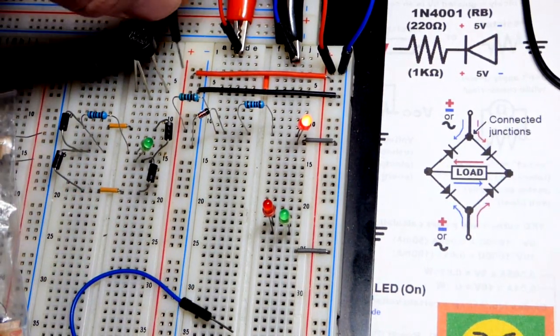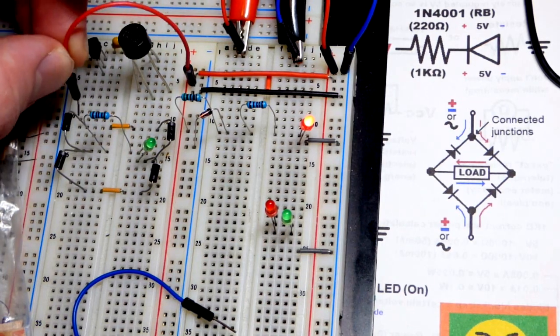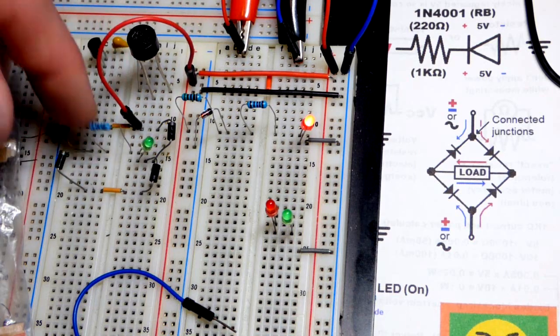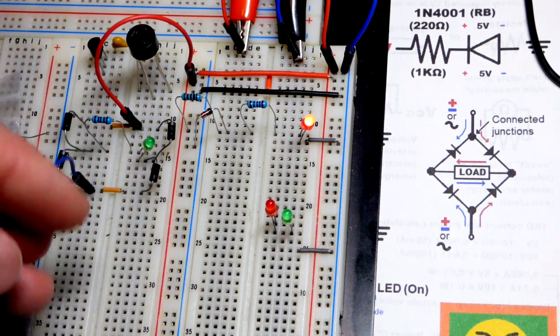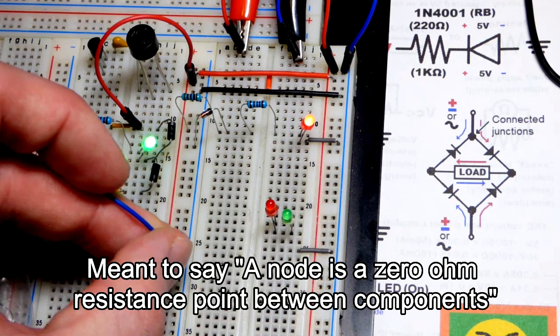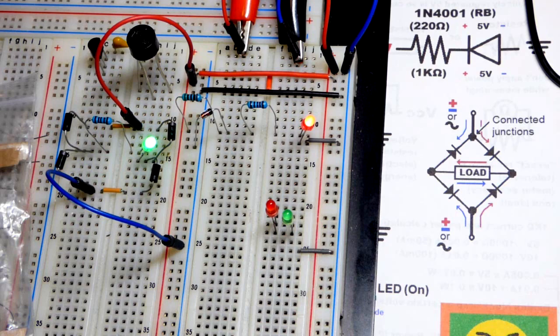And now we can zoom back and look at that, and we'll have this on there. Usually I work my way positive down to negative. So we've got that jumper there to the positive rail, and we can go anywhere along this node, wherever these components all connect. That's a node. If there's a direct 0 volt connection between a bunch of components in one spot, that is what's called a node. So there you can see it lit up.